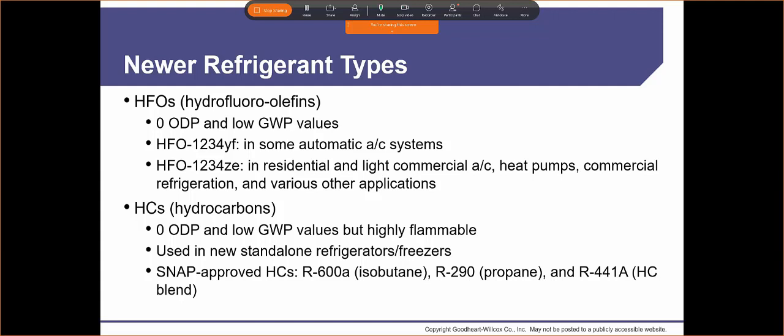Okay. Why is that a concern? Well, we're working on equipment. When we're working on pieces of equipment, if refrigerant were to leak out, normal refrigerant is going to displace oxygen. So if there's a refrigerant leak, get out of there. We don't want to be in there. We want to make sure that there's ample oxygen. So if you're in a confined space and there's a refrigerant leak, get out. We're not going to mess around with it. Let it air out, let it leak out, whatever the case may be. There's just nothing you can do at that point. You don't want to kill yourself over something.